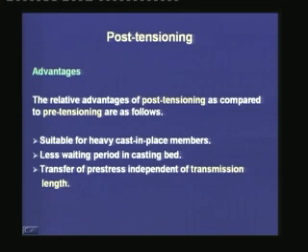If a bridge deck is heavy, then it can be cast in place and the post-tensioning operation is done at the site where the deck will be. Or else, if there are provisions for shifting the bridge deck from the casting yard to its final location, then the member can be precast in a yard. It can be post-tensioned after the member has hardened, and then it can be shifted from the precasting yard to its final location.